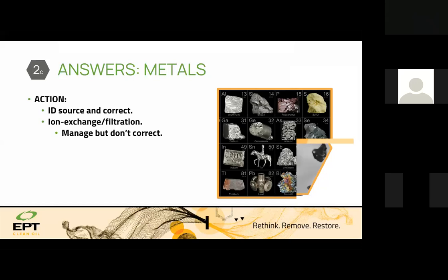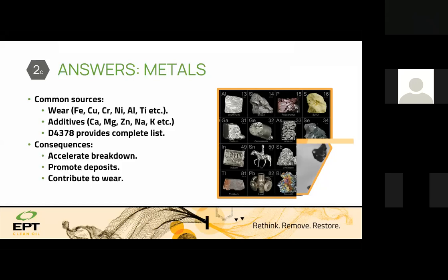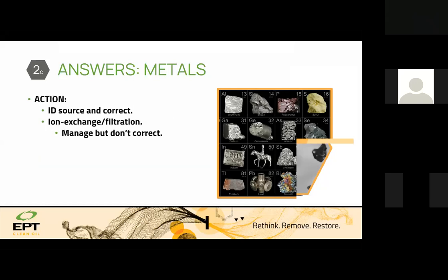But remember, filtering particles, improving particle counts, or improving the elemental analysis of these elements doesn't solve the problem. So once it starts to shoot up, let us not focus on the fact that we are removing it. We need to look at the source. It's being generated, the problem is going on.